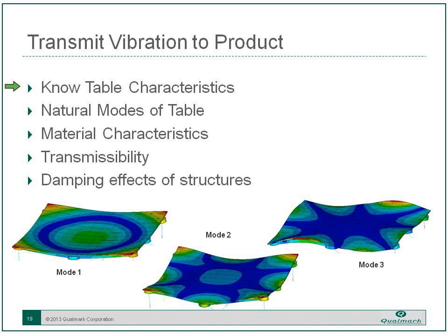It's flexible. It has its own modes, and here you see some diagrams of the three primary vibration modes of the table. We always recommend, if you're fixturing multiple product onto a single large table, that you fixture in quadrants, because as you can see from these graphics of the first three modes, we tend to have uniform quadrants. And if you fixture something heavy in the middle here, you can dampen out this main first oil can mode and reduce the total drive into the product.